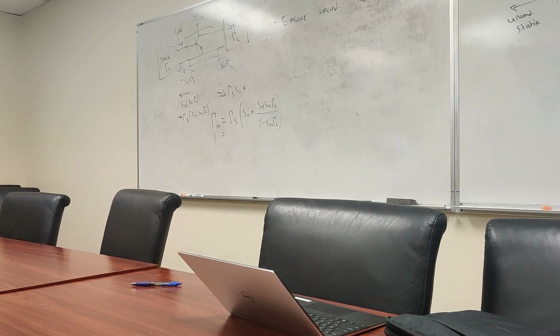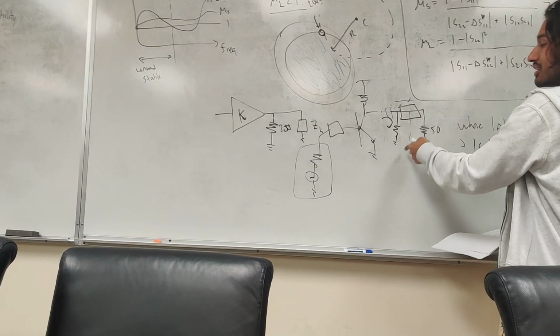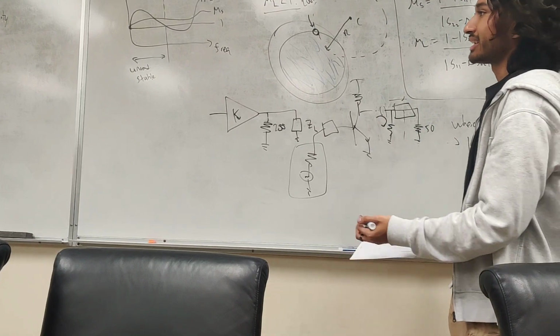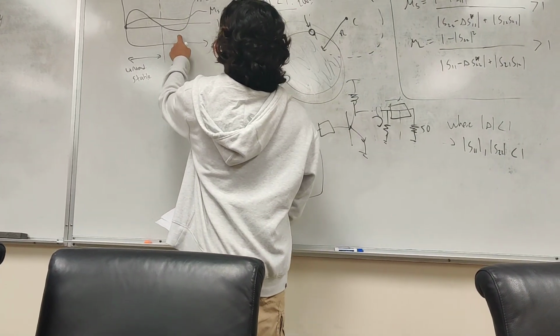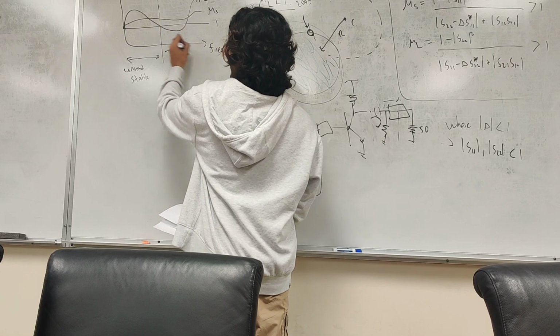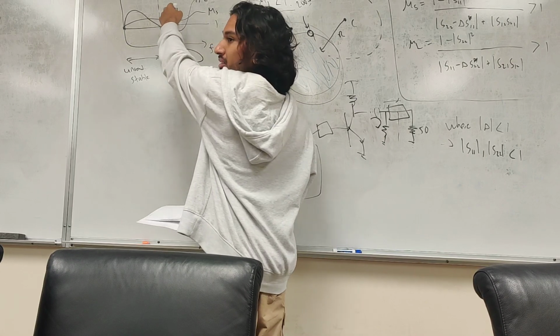Well, this looks like a resistor, right? If we insert a resistor here, it's going to degrade our output impedance. It's going to make some signal go this way, some go that way. Not all of it goes here anymore. So it introduces loss. And generally speaking, if we have something like this, we want to insert loss in these frequencies to bring this up.